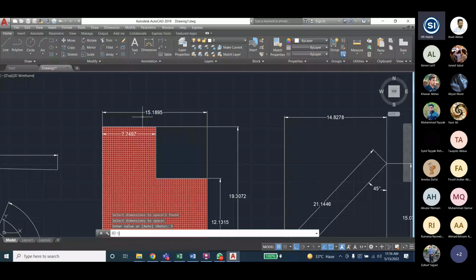Yes, you will select the first line, that will be fixed and the second line will move, okay? Because I selected it so it's moving. So Control Z again. In the dimension space I will select the lower one as first so that it should be fixed, and the second one this one, and then press enter and then press, for example, 3.